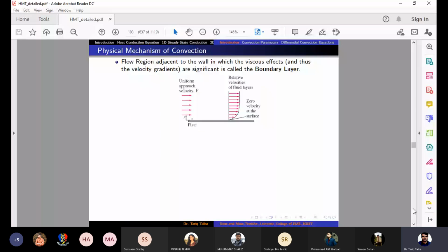I discussed the velocity profile in the last class. I showed you in terms of molecular development of the boundary layer that the first molecule, because it is at rest, has the same velocity as this stationary surface. Then it would apply a drag force on the next layer, so the velocity would be a little bit less than the free stream velocity.